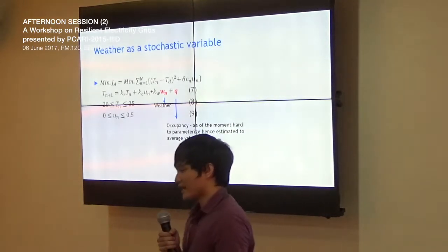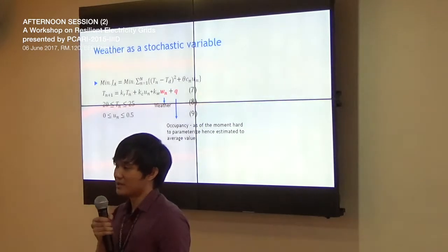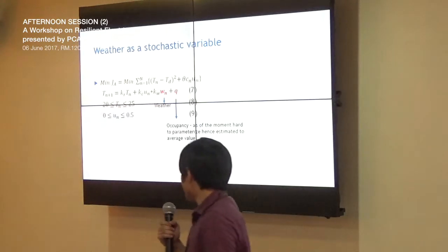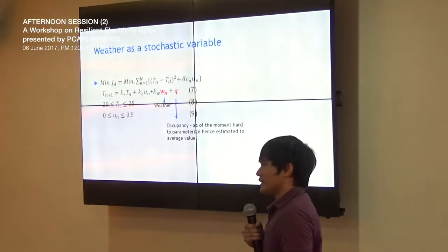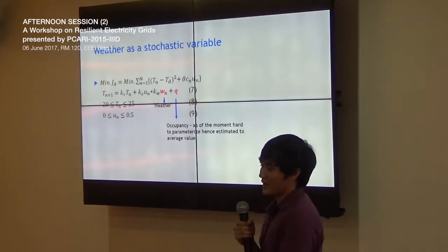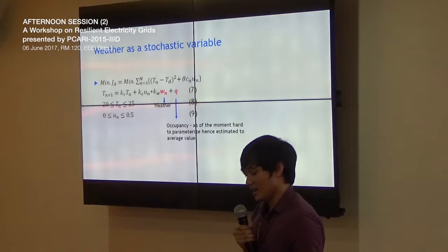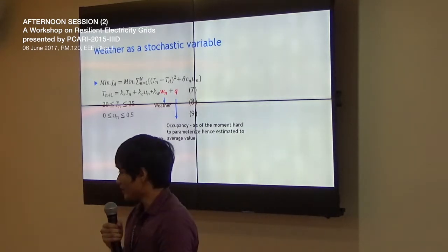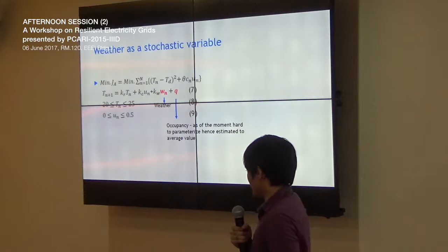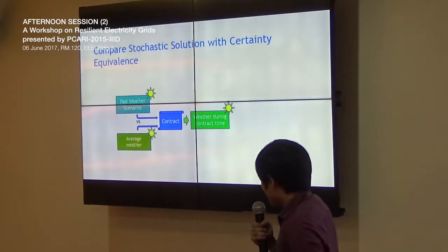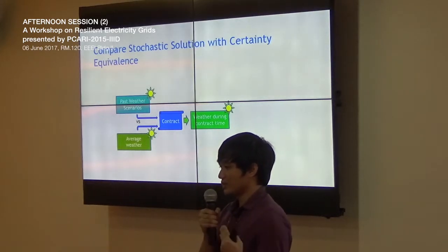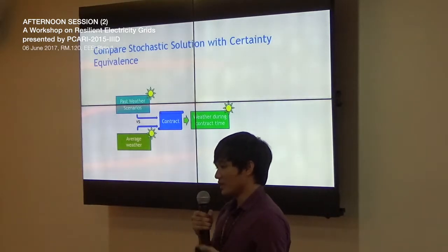But then again, in the model itself, you're really accounting for the stochasticity or randomness of what would happen in different weather scenarios, for example. So you have to incorporate that in the optimization problem. Another thing is that, in the model, occupants certainly provide a lot of heating load to the HVAC. That's also stochastic in nature, but as of the moment, it's not approximated, it's just estimated. So what I've done is use past weather scenarios to approximate a solution that would be robust to, say, a longer contract period.